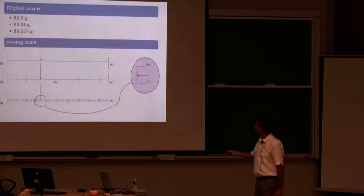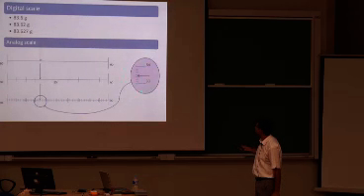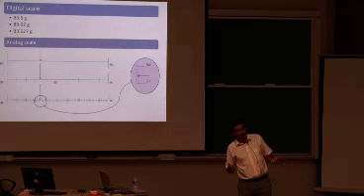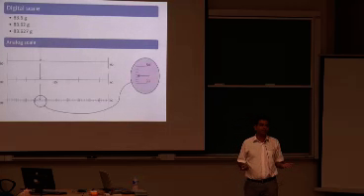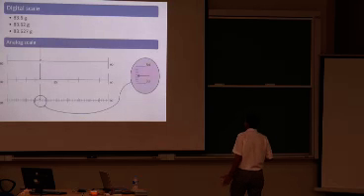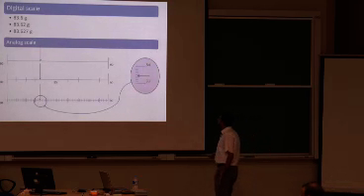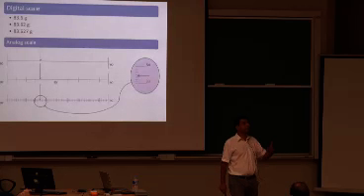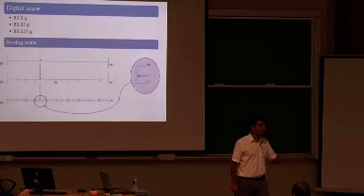Likewise, if this is your gradation, and I zoom into the gradation here, so this is the position of the pointer. Can you tell me what possibly the true value of this mass could be? It could be anywhere between 83.4 and 83.5.